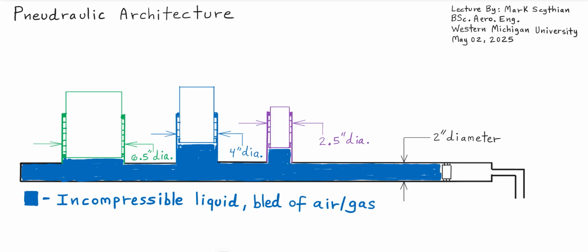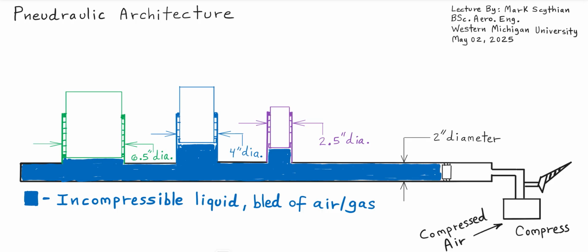Then on the input side we connect an air compressor, compressed air. And so we connect this to a valve, and then we introduce compressed air to exert the input force. So the force in this case is the pressure, air pressure times the piston area, because we know that pressure is the force divided by area. Case in point, pounds force per square inch, PSI pressure.